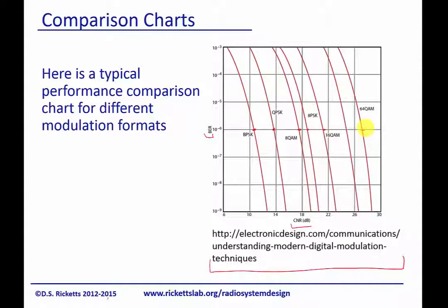And I think a really interesting one to look at right here is 8 PSK and 8 QAM, because if you remember, we talked about before, if here's our 8 PSK and we've got an 8 QAM, so maybe it goes like this, we can actually have the same intersymbol distance for lower overall power than we did over here.